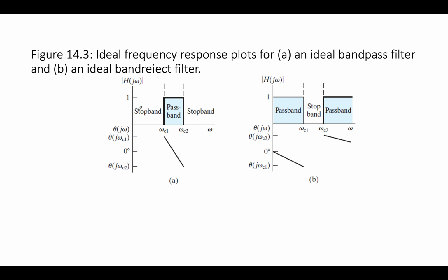And then finally we have the stop band. In this case, you're passing everything except a finite or limited range. This is most commonly used to do something like block 60 hertz noise. You try and make this a very narrow stop band so that if you have a lot of 60 hertz noise in your lab that's interfering with your measurement, you can design a filter that'll act to stop that.